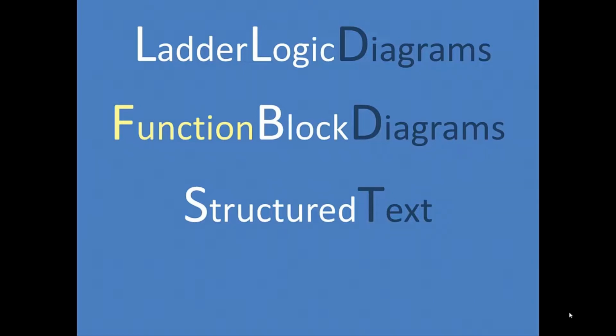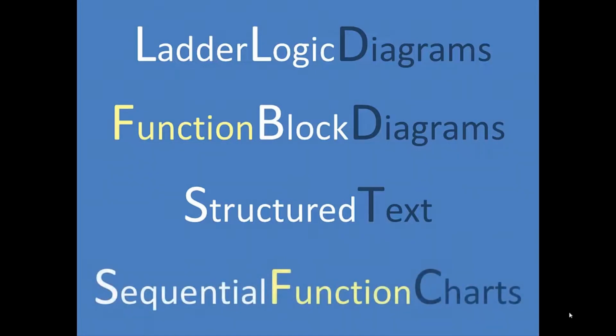With structured text, you have to read it. And then, of course, sequential function charts. Now, sequential function charts are not really a language, even though if you were to ask anyone in the field what are the languages available in the Logix engine, RSLogix 5000, they would probably say ladder logic diagrams, function block diagrams, structured text, and sequential function charts. Sequential function charts is only a language in the sense that it supersedes the program control available through these other three real languages.